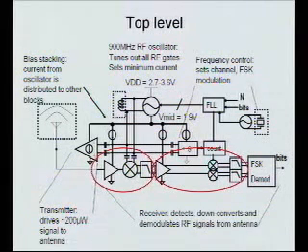So if it's sleeping most of the time, when does it know to wake up to listen to the signal? Because this little bit does not sleep. You can actually implement a low frequency crystal oscillator for about half a microwatt. So this guy just runs all the time, and it has a counter sitting on it.